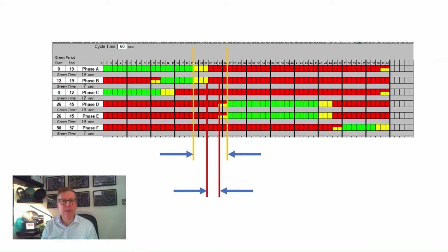However, it may be found that the required period of separation between specific phases will need to be longer than this to account for the geometric design of the junction, with the distance between each phase being of paramount importance, along with peripheral issues such as the topography of the junction also requiring consideration. Longer intergreen periods are achieved by running the red aspect of the appropriate phases between the leaving amber and starting amber periods of the respective phases.